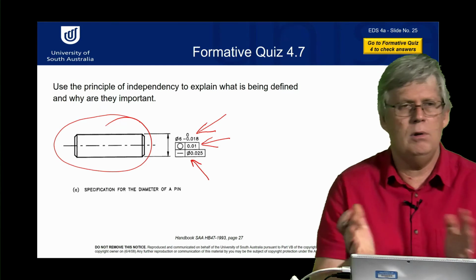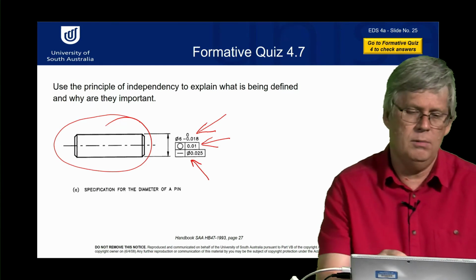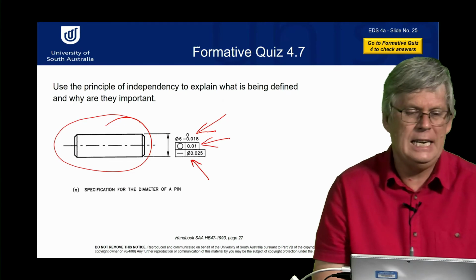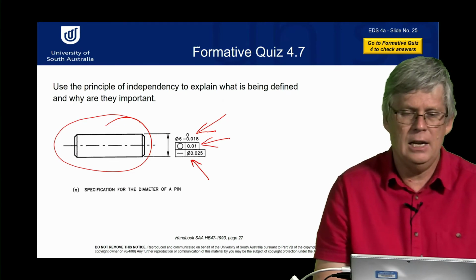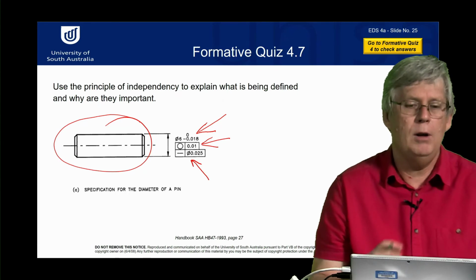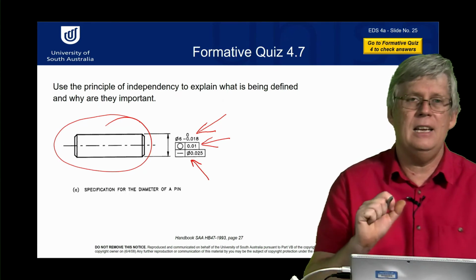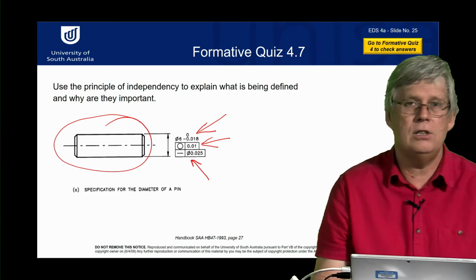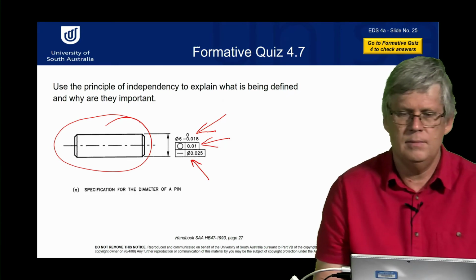If you say, oh, well, it's outside and it's still suitable, well, then maybe you should look at what values you've got and whether you need such precise values in there as a designer. So they're very important. When you're putting these values on, you are saying accept if it's within the tolerance, reject if it's outside of those tolerances.